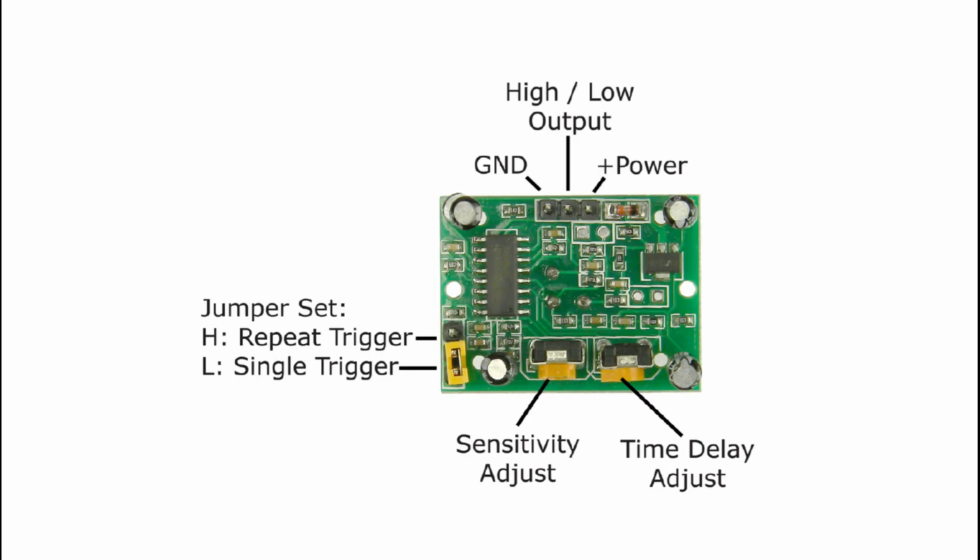I didn't encounter any issues with my PIR sensor, but I did make some adjustments during later testing. Coming out of the box, the PIR sensor seemed to only pick up on motion from the minimum of its range, at about 3 meters. For maximum security purposes, I reasoned that the system would benefit from motion detection at its maximum range of about 7 meters. I adjusted this by turning the sensitivity adjustment potentiometer clockwise.